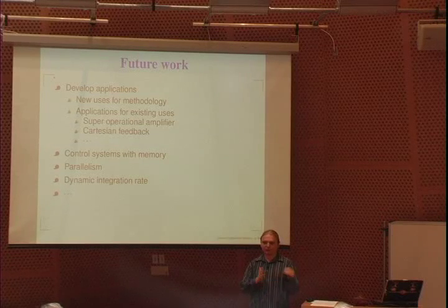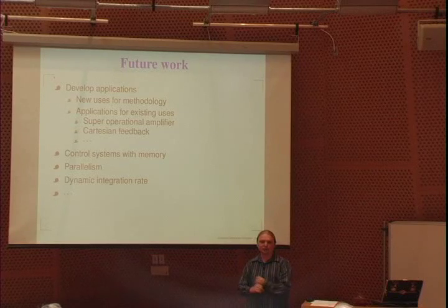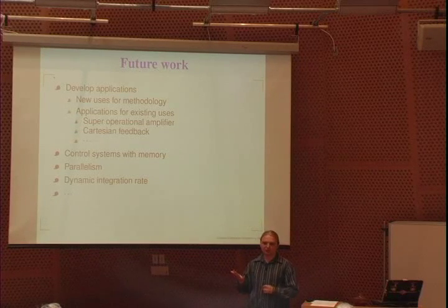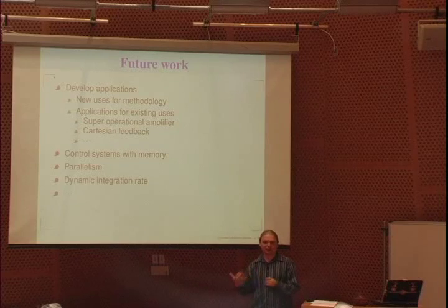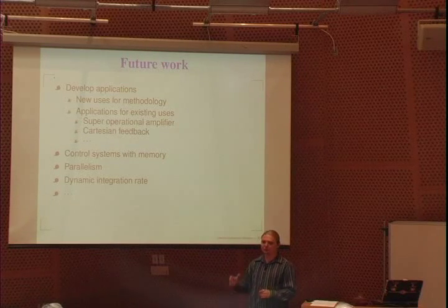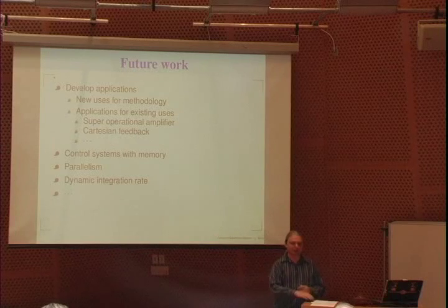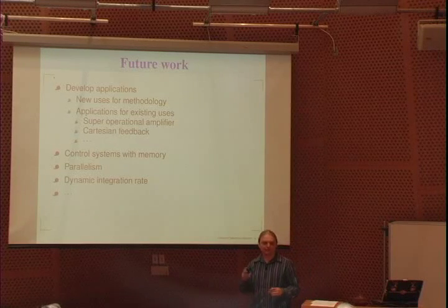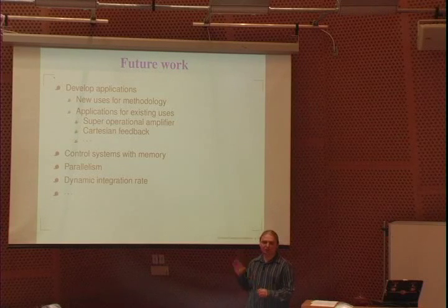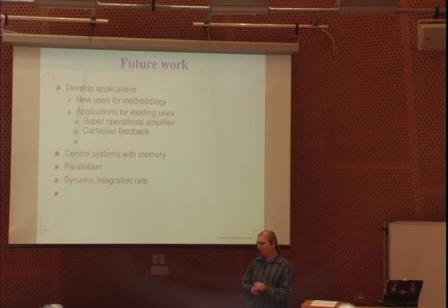So you can, for example, instead of making a stage that's 10 devices wide, make 10 different stages and adjust the bias current levels to them, sort of to take a combination of those stages that minimizes distortion, possibly even put in a few stages backwards that have low gain, high distortion to subtract off some distortion, and try to linearly combine those stages to minimize distortion. There's obviously some hard engineering problems to doing that, but that's a reasonable use for this.